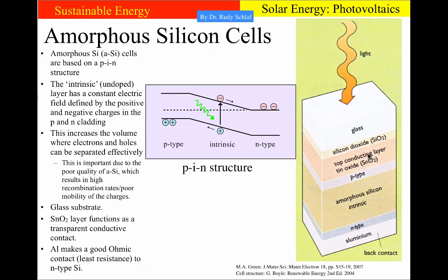The metal grid requires patterning, and it also has the disadvantage that light is being absorbed in the metal grid that is not available for the electricity generation in the solar cell. The disadvantage of the conducting tin oxide film is that its conductivity is considerably lower than that of pure metals, and that generates an ohmic resistance in the top contact, which lowers the efficiency of the solar cell.